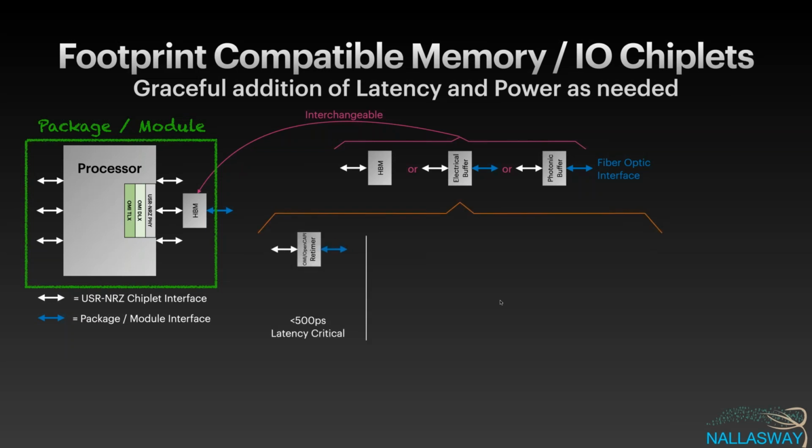Taking the electrical buffer, if we wanted to connect to local memory like memory DIMMs to get more depth, which HBM can't give us, we could simply then put an OMI retimer that would allow us to actually reach that DIMM with a minimum of latency.